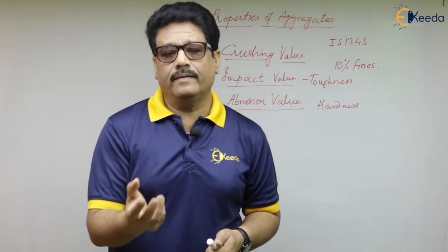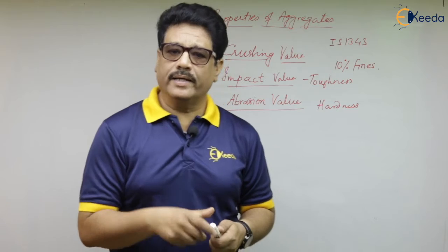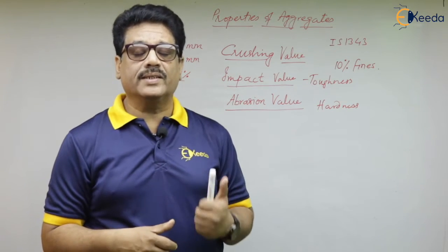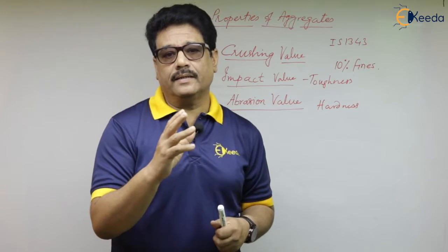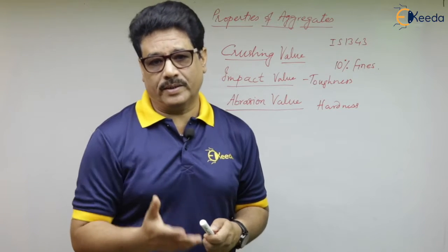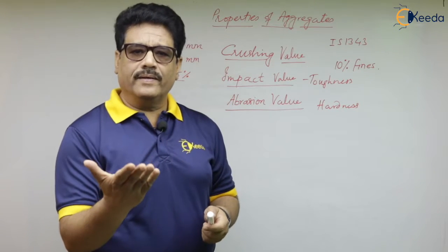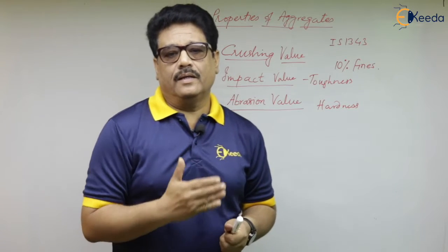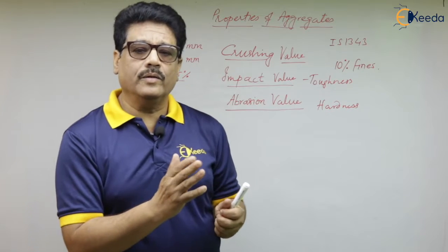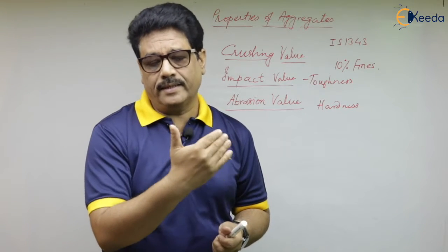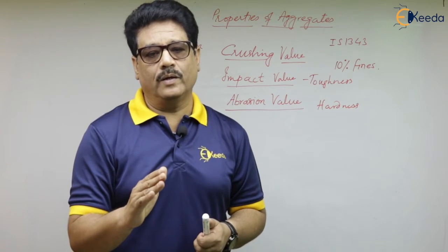We have to measure it, and the calculations required we have to do them, and then we have to report that impact value in percentage. So anything less than 30% is very important for road surfaces, and in other concretes maybe 30 to 35%, but always less than 45%. More than 45% is not allowed, but this is again a norm which has been revised recently, and for both now the code says that 35% is the highest value.